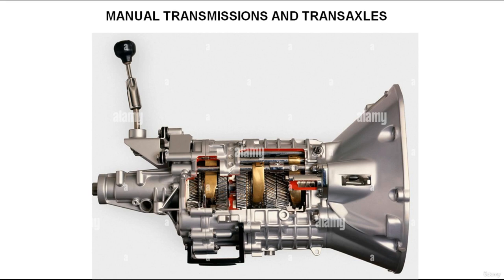During normal operating conditions, power from the engine is transferred through the engaged clutch to the input shaft of the transmission or transaxle. Gears in the transmission or transaxle housing alter the torque and speed of this power input before passing it on to the other components in the drivetrain. Without the mechanical advantage the gearing provides, an engine can generate only limited torque at low speeds. Without sufficient torque, moving a vehicle from a standing start would be impossible.